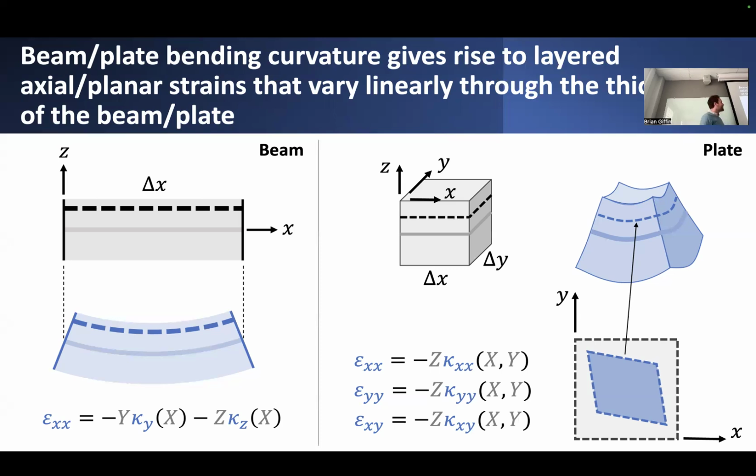In the simple case where we're just looking at, let's say, a beam that's bending only due to deflections or transverse deformations in the z direction, we can look at some neutral axis of this beam, and before and after deformation, assuming that this beam is only undergoing bending deformations, we can reasonably assume that this neutral fiber is not undergoing any kind of axial extension or compression.